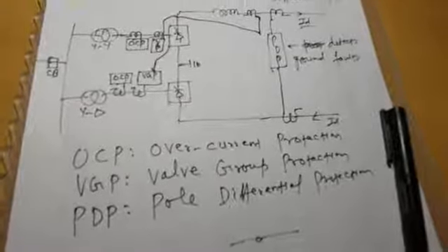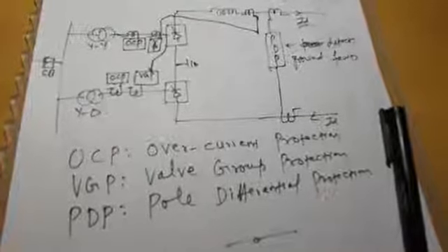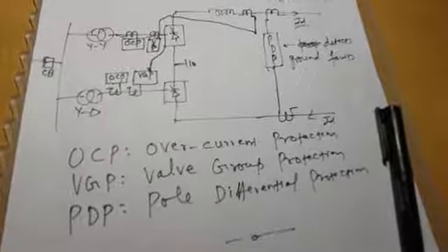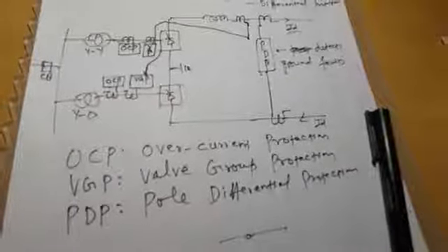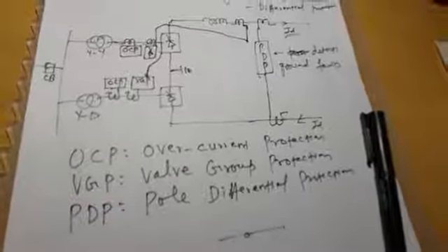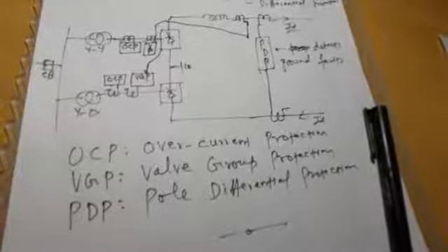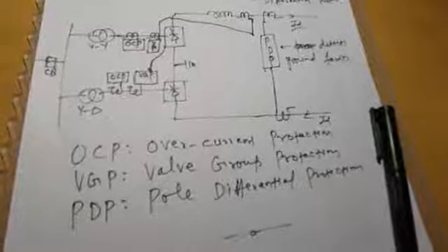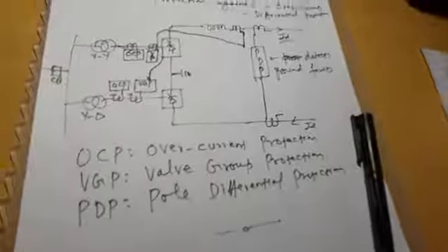And then overvoltage on the AC side will originate on the DC side, and in fact on the DC side, if you have many converters in series, then the overvoltage will be the overvoltage of one converter multiplied by the number of converter groups. So the overvoltage on the AC side will cause a very large overvoltage on the DC side. And then this loss of load is also responsible for overvoltage in your HVDC converting station.